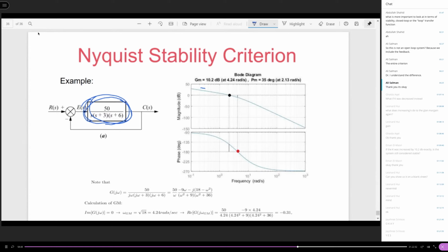Like what I said, first let us do some prediction, because I have a third order denominator for the open loop system. So you can predict that if you draw the phase plot, the phase is going to be between 0 and minus 270 degrees.